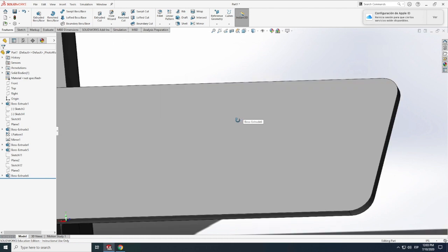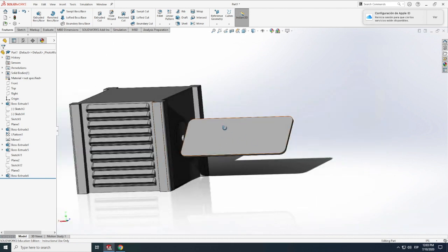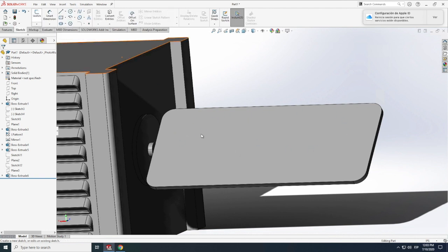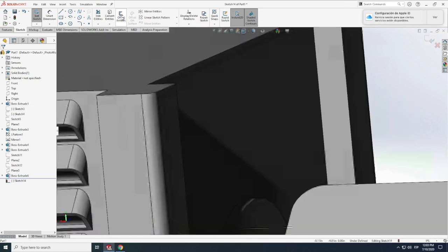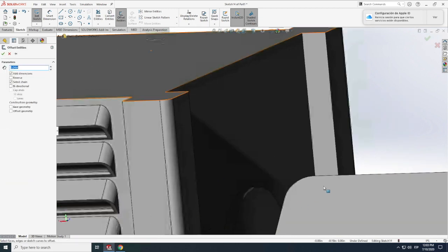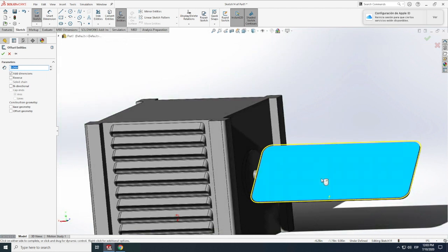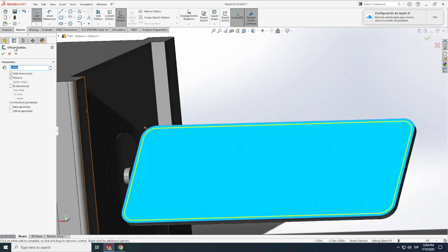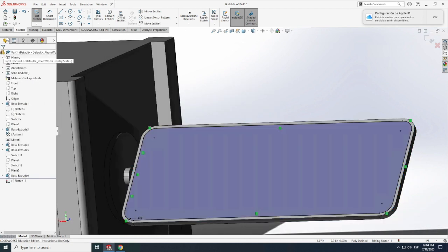And now what we can try then is some designs in there. This could be like the shell. We can go sketch. So here's something interesting that we can do. We can go offset entities of this thing. There we go. And then reverse that. Yeah, let's go 0.05. Let's extrude. All right, let's say okay.